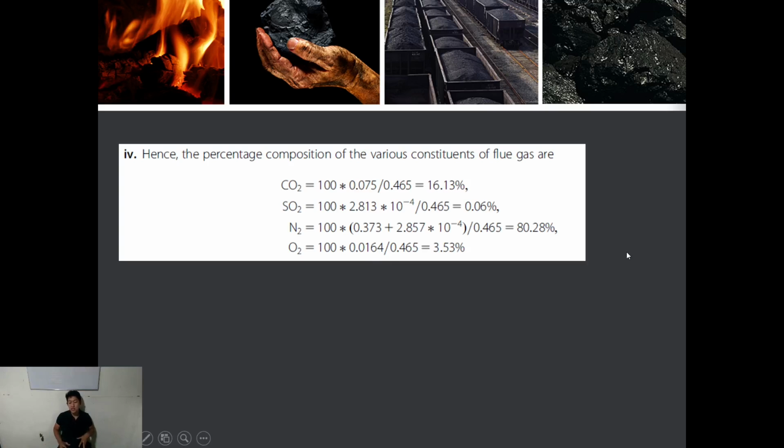So that is just the use of the equations. In your project, you need to determine the amount of air and the amount of flue gases. Okay? You will use these in order to size your fans. Okay? That's all.